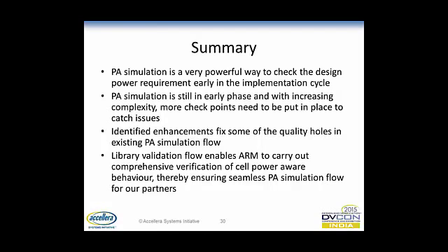One example I mentioned was the restore protocol requirement. Let's say the simulator is not capturing that from the Liberty and it's not modeled anywhere else, then it will just pass, saying that whatever you restore, your simulation environment will show that your value is getting restored, and everything works fine in the simulator. But once it goes to silicon, then probably you will see the failures. So these are things not yet addressed by the simulators, which need to be fixed.